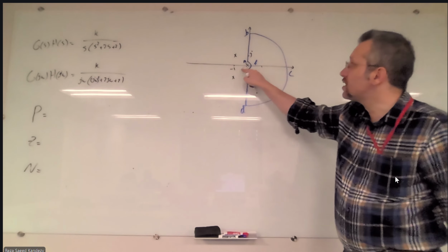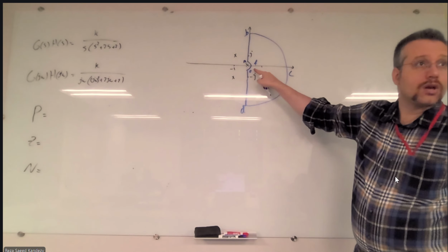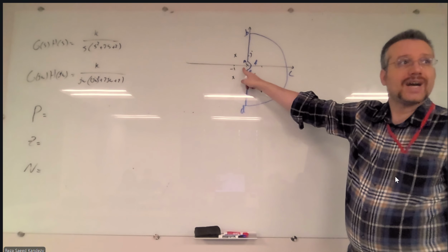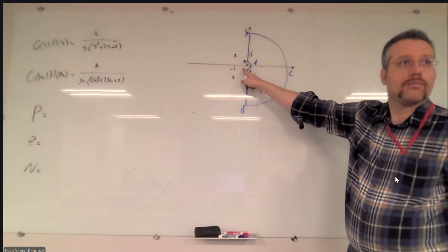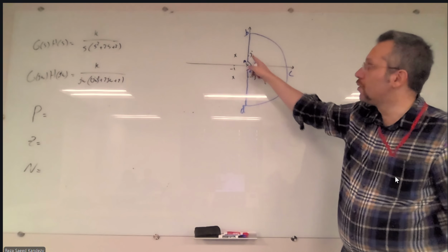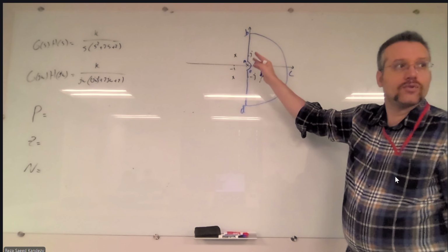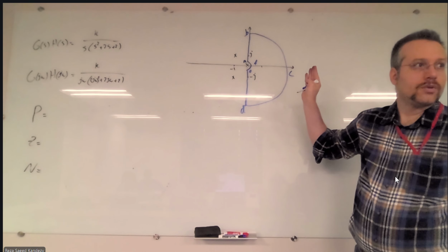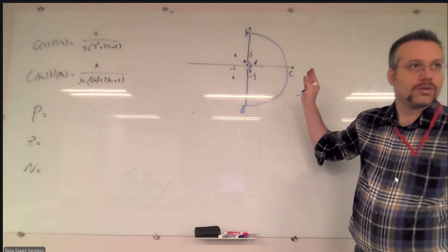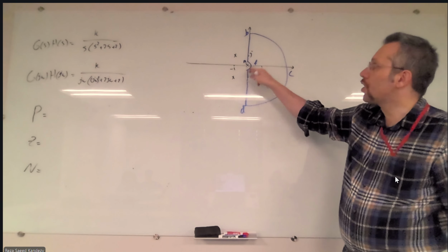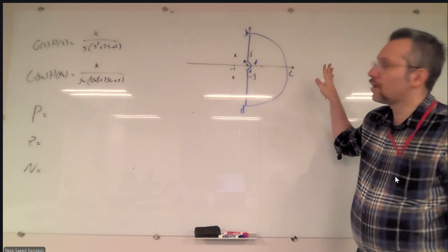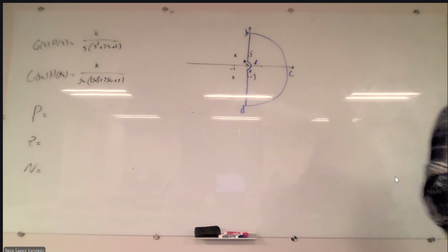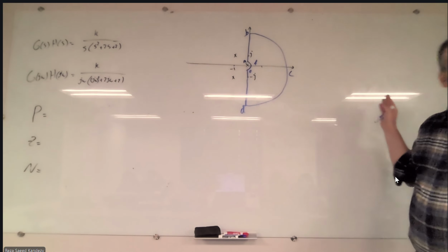Now, since we consider the contour to the right of this pole, we don't consider this pole as a right hand side pole. Are we good? If we would go the other way around, then we would have one pole to the right of our contour. Is that clear what I'm talking about? Just to repeat, all of our contour is to the right of all the poles, so we don't have any poles or zeros on the right of our contour.